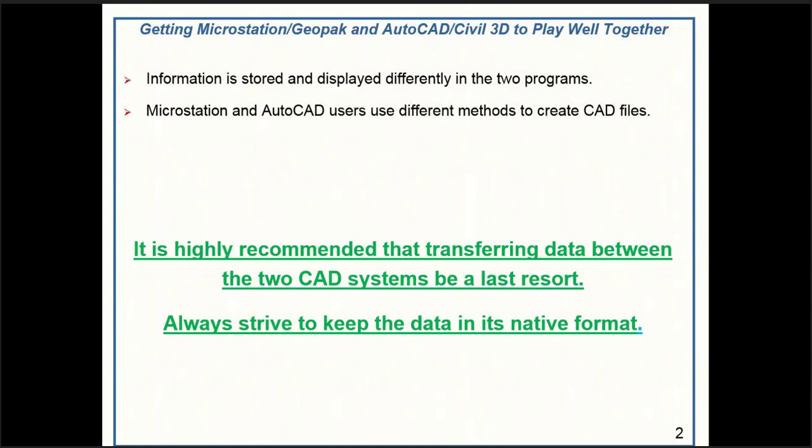Before you begin this process, in your Civil 3D drawings, you have objects such as surfaces, alignments, parcels, and such that are exported from Civil 3D, and these will function much like any other regular AutoCAD data. When I say regular AutoCAD data, I mean things like lines, arcs, circles, and such. For example, a surface object that's being transferred from Civil 3D is basically converted to polylines, so only polyline editing is allowed in plain AutoCAD or MicroStation platforms.